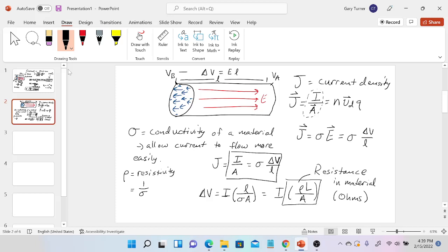And if you think about it, this formula should make some sense. You have some material, whatever it is. It doesn't have to be an iron or copper wire, but it can be. And the longer you make your material, the more atoms you put in the way of any given path. And so the longer you make your material, the more atoms there are for each individual electron trying to flow to bump into. And that is essentially the root of what resistance is. The more material that will impede the flow of your electrons, the higher the resistance of the material.